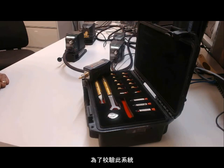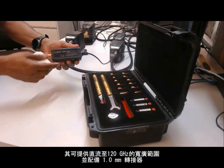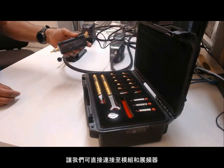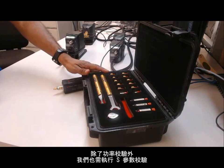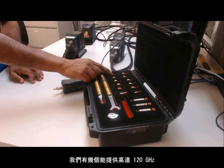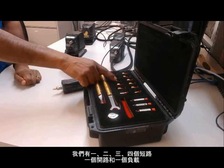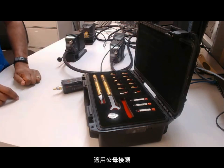So in order to calibrate the system for power, we use a broadband power sensor, which is USB based. It goes from DC to 120 gigahertz, has a 1 millimeter connector that allows us to connect directly to the modules, the frequency extenders, and calibrate them for power. In addition to that calibration, we need to do an S-parameter calibration. As you heard in the presentation, we have several shorts that provide us with the broadband calibration capability up to 120 gigahertz. We have short 1, 2, 3, and 4, an open and a load, and this is for the male or female connectors.